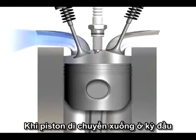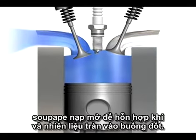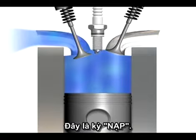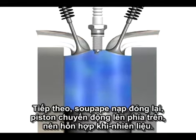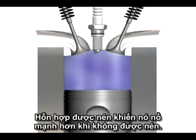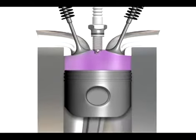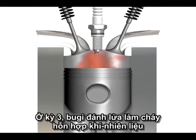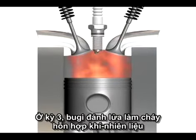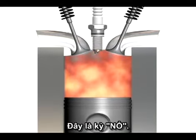As the piston moves on its first downward stroke, the intake valve opens to allow a mixture of air and fuel to fill the combustion chamber. This is called the intake stroke. Next, the intake valve closes and the piston moves on an upward stroke that compresses the air-fuel mixture. The compression of the air-fuel mixture will make it combust with greater force than if it were uncompressed. This is called the compression stroke. Third, the spark plug ignites the air-fuel mixture, causing it to burn explosively, which forces the piston into another downward stroke. This is called the power stroke.